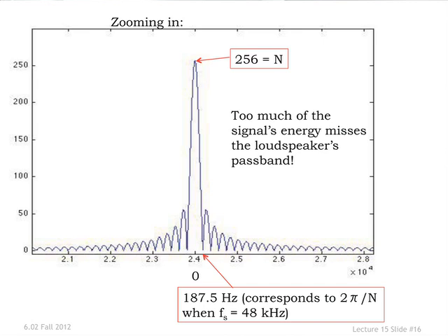This is not a sinc, it's a sinc-like function, because if you extended it, it would go back up again. It's got that period 2 pi exactly as it should. But for all intents and purposes, for small values of frequency, the sine of omega over 2 here is essentially omega over 2, and this is a sinc-like function.